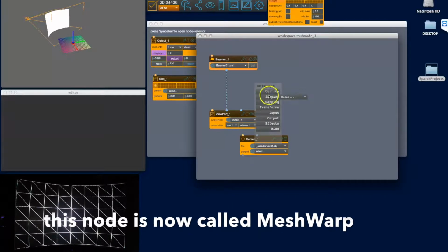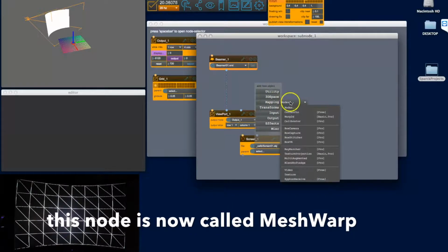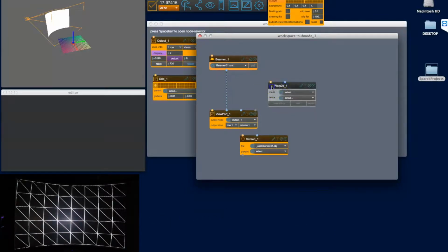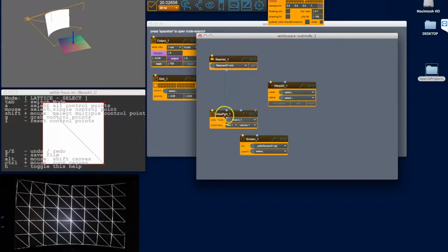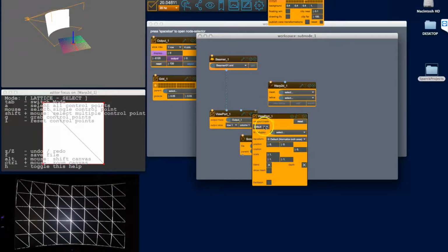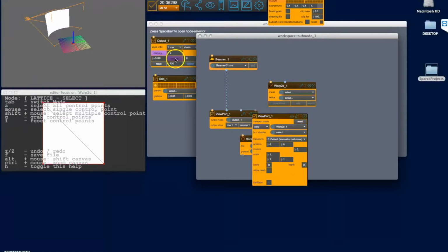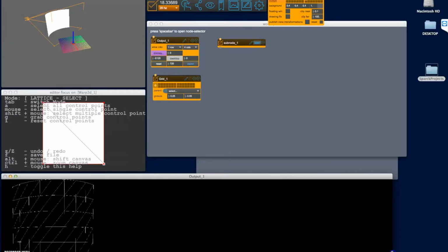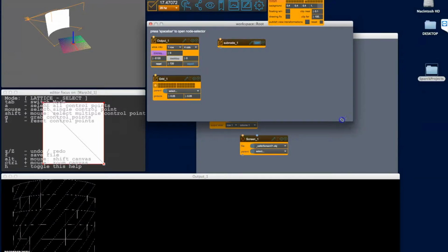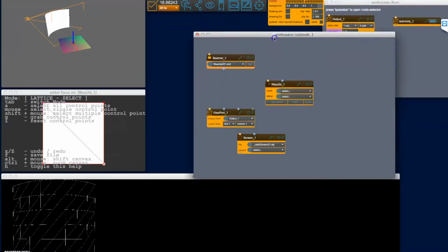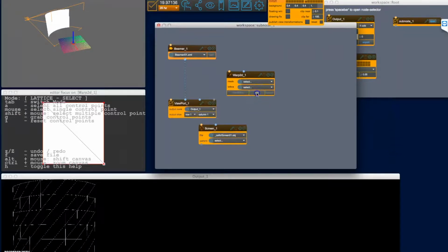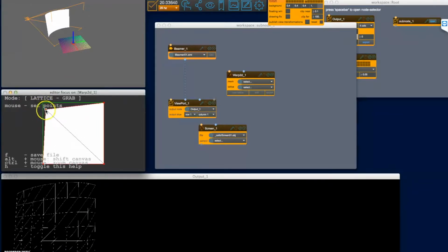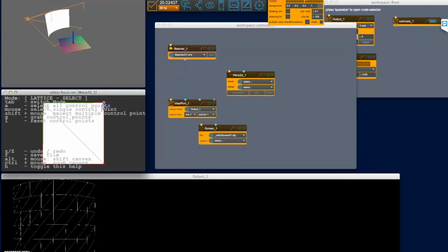So I'm going in here, go mapping, I'm going here into the viewport and tell the viewport that instead of, I'm going to select the warp 2D here, this one here. So if I quickly switch back the output, look at the output, place that one up here, and press edit. What you can see now is I can actually manipulate and make corrections.